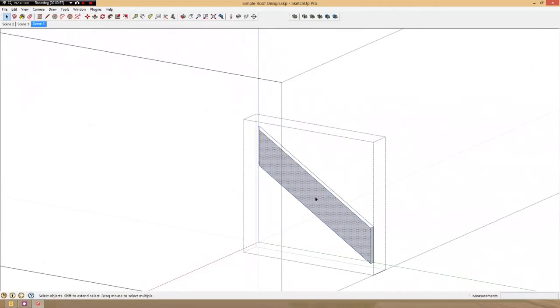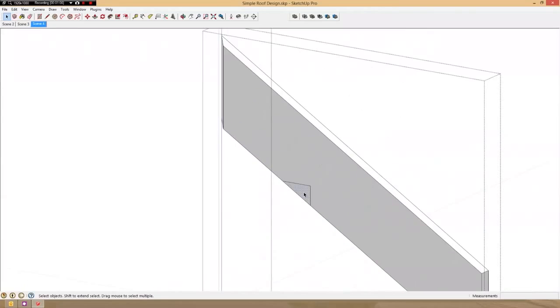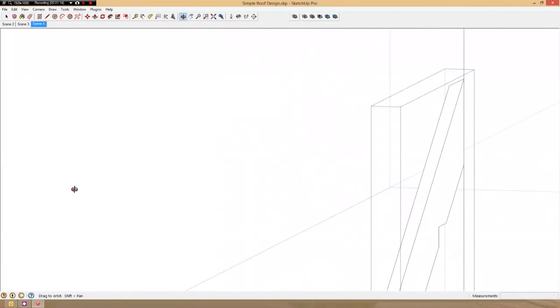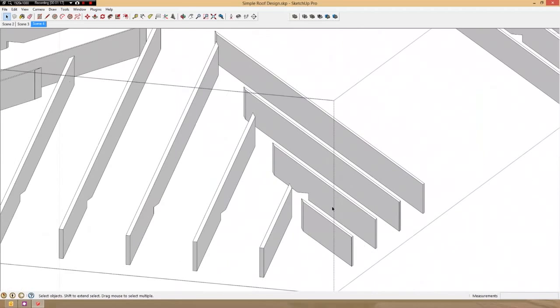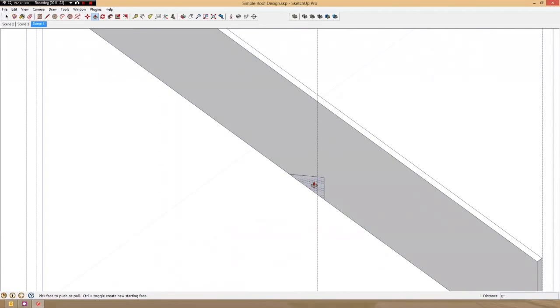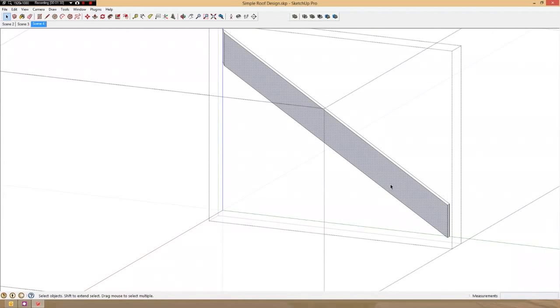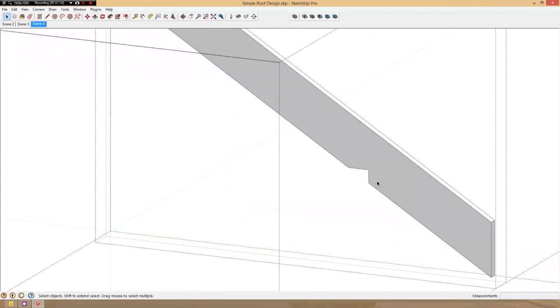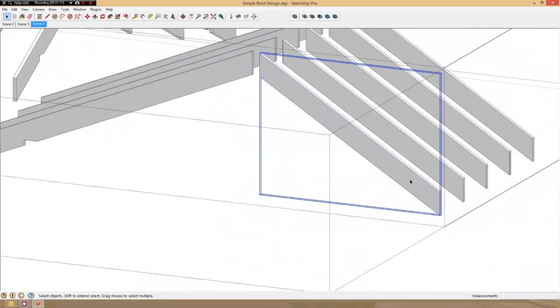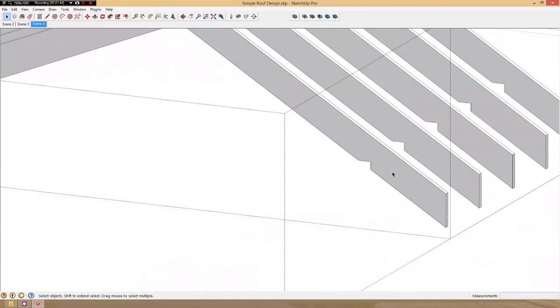So what I do is I select each member individually, select one face, intersect face with model, select the push-pull tool, and then drag it over, select the far edge, and that is done, and so on. Double click this time because it will duplicate the push-pull. These are components, so all we have to do is edit one, which is what I love about components.